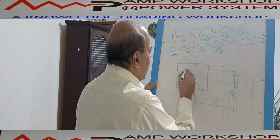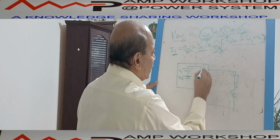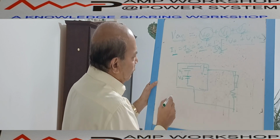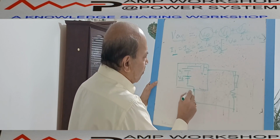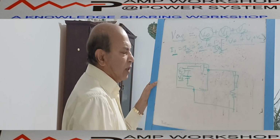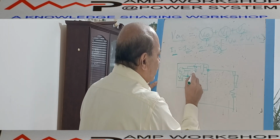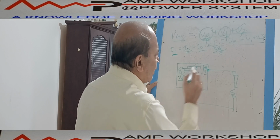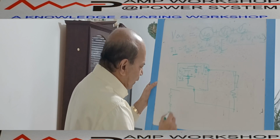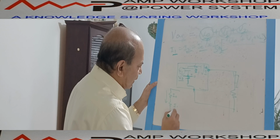Then there is another voltage here, this is negative, this is positive, this is V1. Then this is another voltage, negative, positive, it is V2. And these three are connected together. If we do it in this way, what is the voltage difference between these two? VAG equals V0 plus V1 plus V2, because all are connected in series. Again, the current flowing through this is I0, through this is I1, and through this is I2. These three are equal. When is that possible? There are three impedances. When they are connected individually, the current flowing through this is I0, this current is I1, this current is I2.